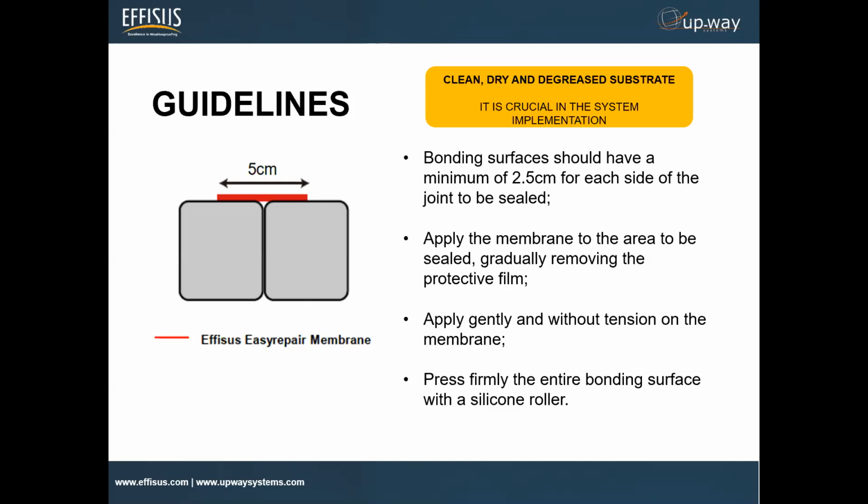The only thing I would like to highlight here, you see in yellow, is that the substrate must be clean, dry, and degreased of any grease. This is really important for the application. Very commonly, some other products have been applied, so we recommend to remove them and clean up the area.